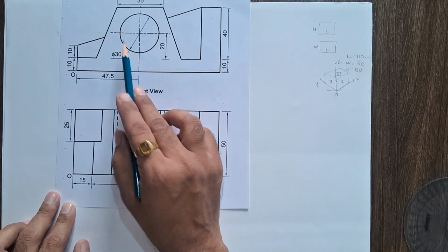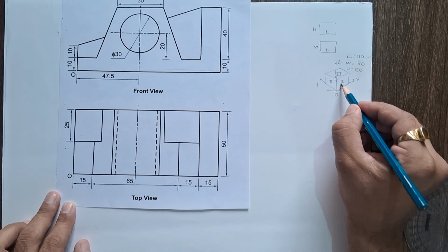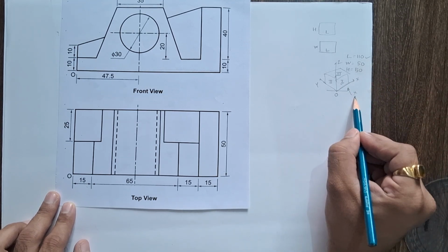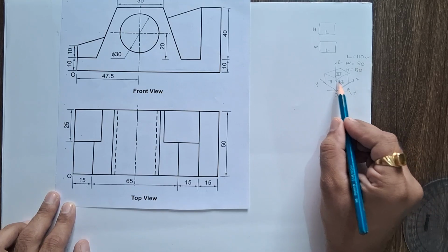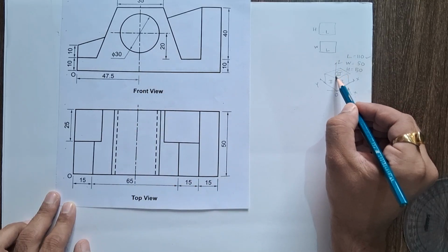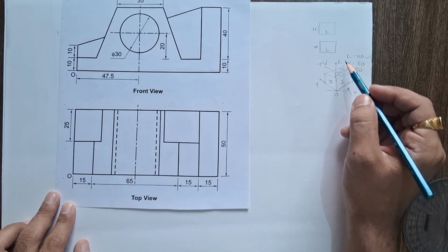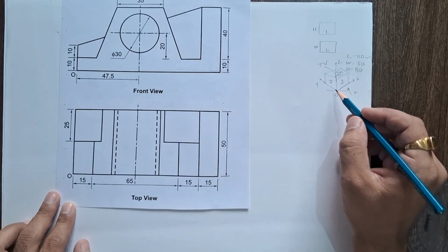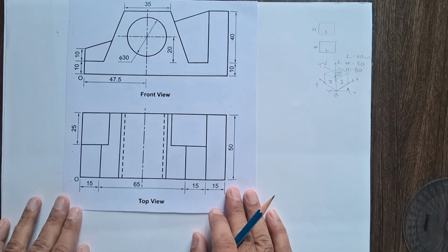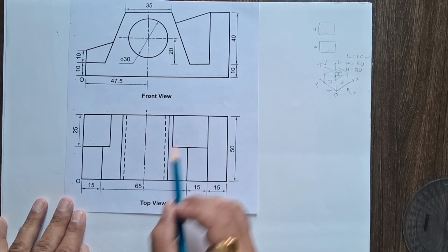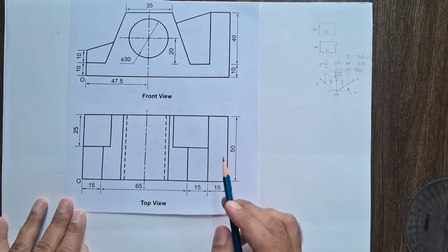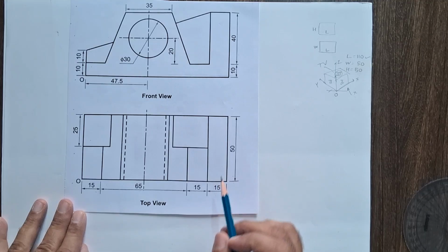This front view, we will get it in plane 1. Observer looking direction is x. When the observer looks from this direction, in plane 1 we will get the front view of this shape, and in plane 3 we get the top view. So with the help of front view and top view we can easily draw the isometric view for this problem. Now here, see the problem. From the problem we have already found length, width and height. Now read the drawing carefully, understand the view, then we will see the solution for this problem.